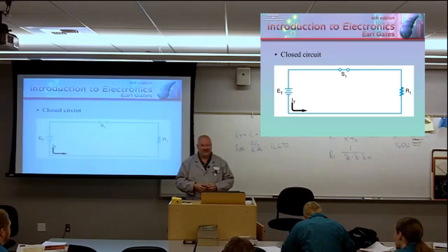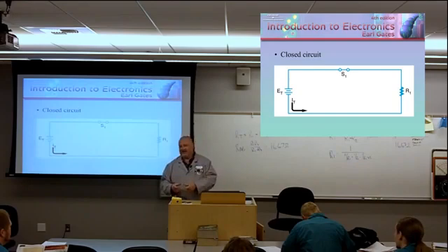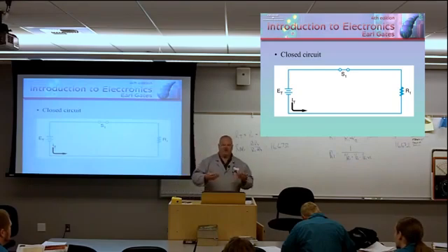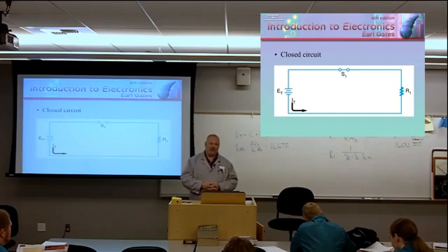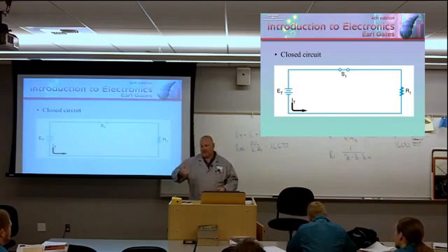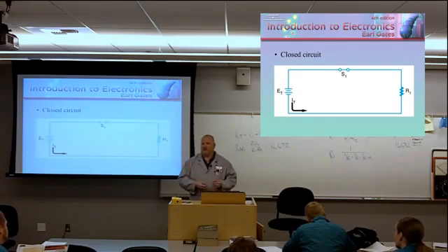I'll loan you my pressure washer. But only plug it in a dedicated outlet, and do not use any extension cords. It's right on the label. It's not that I'm that smart a guy, I just read the tag that's on it. This motor requires a lot of current to be effective. You plug it in an extension cord, it doesn't get the right amount of current. Remember that whole thing, the cord gets hot. The hotter it gets, the more resistance, the less current, the hotter it gets. It's a vicious cycle. So I loaned him my pressure washer.